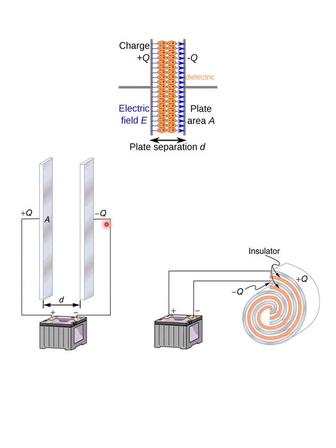But practically speaking, many capacitors are not actually parallel plates. Mathematically, they will function that way, but physically, engineers have gotten a bit creative and inventive in designing different kinds of capacitors. So here's a standard capacitor. You have an insulating material that's the dielectric, and then these, what in the picture on the left are plates, something more flexible, like maybe aluminum foil rolled up. And so we have these cylindrical capacitors. Mathematically, it works the same because those rolled up plates, they still have an overall surface area, and they are still separated by some distance.